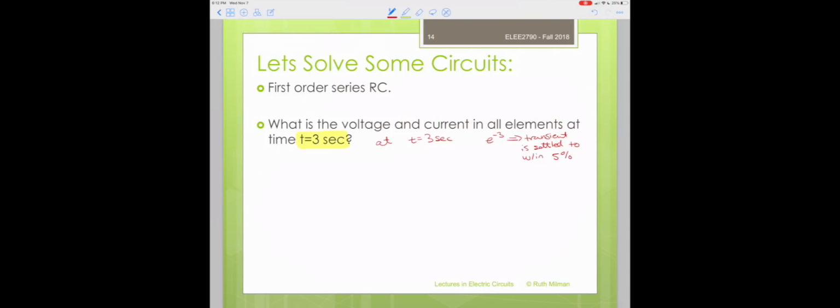So it's up to you in the application that you're doing, but in this particular instance, I'm going to make the statement that I can neglect my transients because of this, and once I do that, I'm simply going to actually evaluate the different extra pieces that we have of the sinusoids. So, no problem. What am I going to do? Let's look at the first one. The source voltage is equal to the square root of 5 times the cosine of 45 degrees plus 2t.